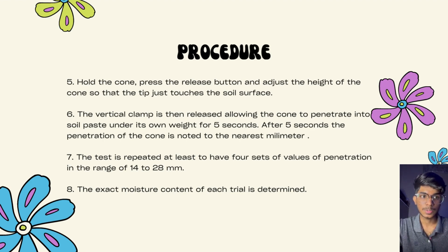Seventhly, the test is repeated to have at least 4 sets of values of penetration in the range of 14 millimeters to 28 millimeters as well. So lastly, the exact moisture content of each trial should be determined.